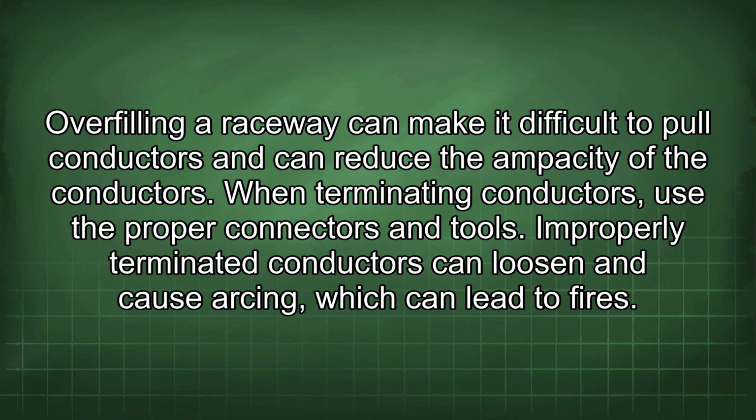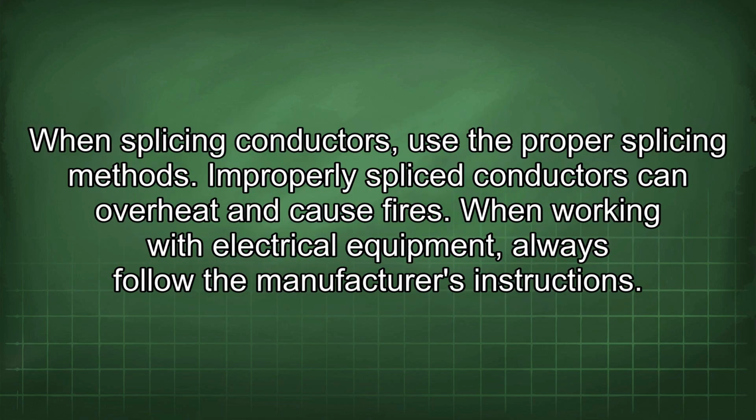When terminating conductors, use the proper connectors and tools. Improperly terminated conductors can loosen and cause arcing, which can lead to fires. When splicing conductors, use the proper splicing methods. Improperly spliced conductors can overheat and cause fires.